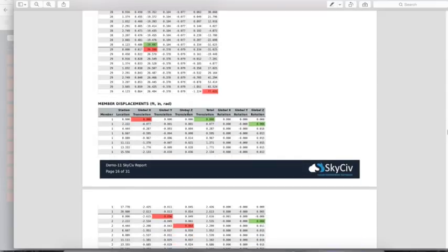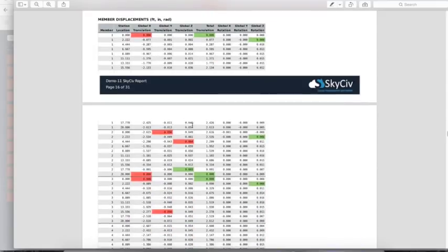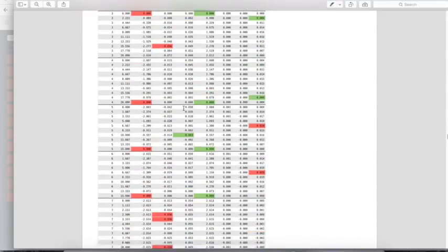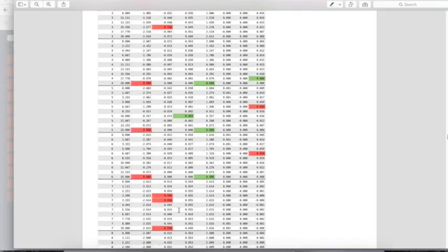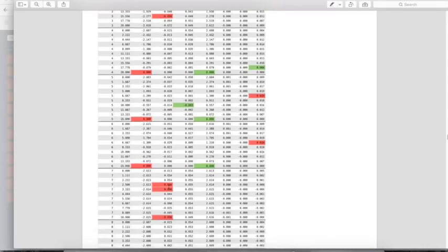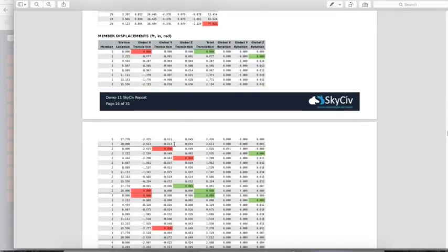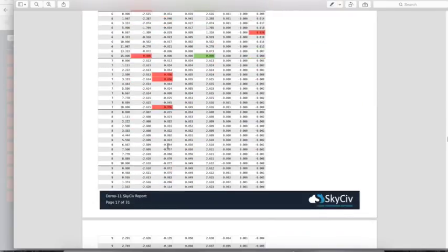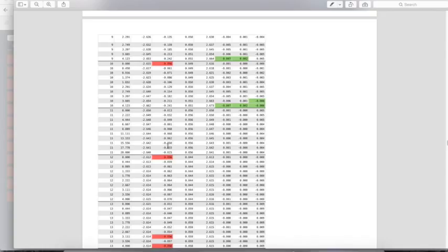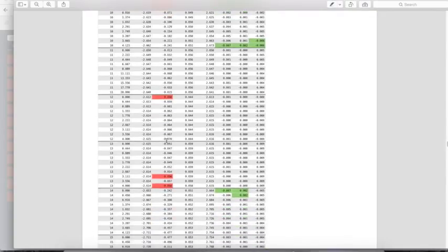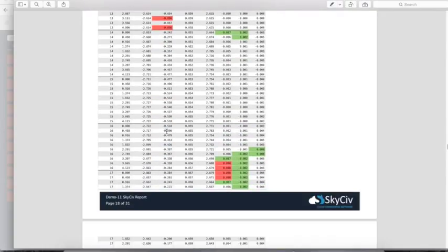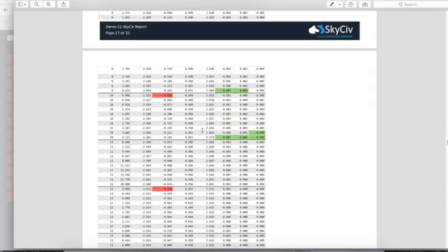So again, looking at displacements, I might want to look at what the max and min displacements are, and if there are multiple ones, it just means that it's the same result. So I can see 0.05 inch is the maximum result in terms of global Y. It might occur a few times within the model, maybe because those nodes are connected all at one spot, but I know that maximum is 0.05, and for this one it's 0.008. Very reasonable numbers.